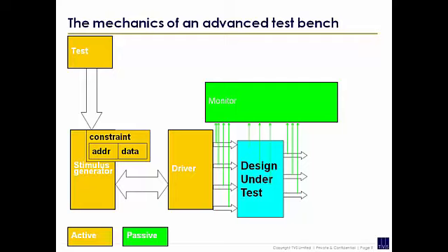So if the designer changes the hierarchy, the designer changes the signal name, and you're tracking that signal name, your test bench breaks. So you have to be very careful with white box. That's why with black box, we always try to do black box. Sometimes you have to do white box. Okay? And then these are transactions.